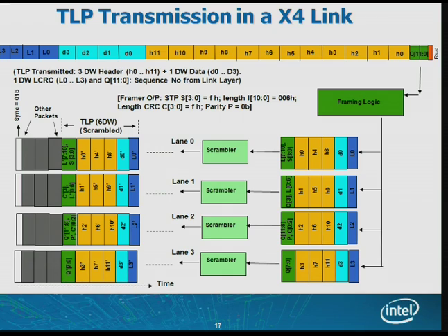This definition of encoding is in a fairly solid state, and I would say we came up with something fairly pragmatic that is not overly complicated. It is a bit more complicated than just simply going with the 8B/10B scheme, but I said previously 10 giga transfers per second would break the ecosystem.